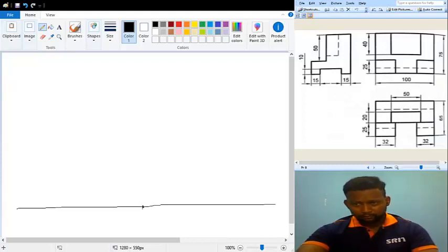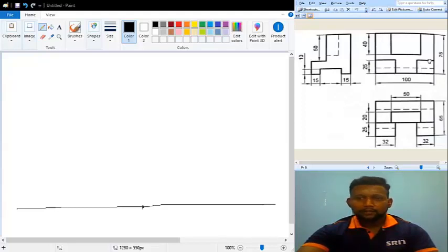Here in the front view you have a length of 32 mm. If you drop down this figure, this is your 25 mm and this is your 32 mm. How am I able to say that it is 32? Since this is 32, if I draw a line over here like this, this also will be equal to 32 mm and this will be equal to 25 mm. So first I am drawing that: this is 25 mm, and this is 32 by 32 and again 25.